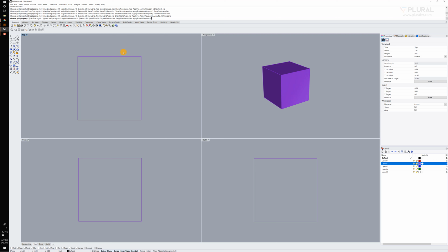Typically in Rhino, if you're in a command, you can hit Enter to end the command and accept the changes, or hit Escape to back out of those changes. Let's say I was drawing a curve in the viewport, and I hit Escape. It undoes everything and doesn't commit any command. If I drag the curve here and then hit Enter, it accepts and ends the command. You can click all of that and then hit Delete.